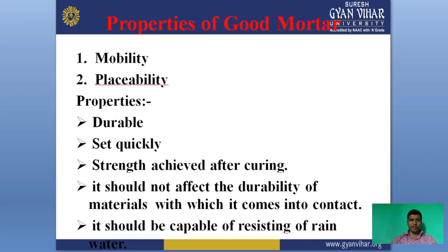The good properties of a good mortar are: it should be durable, meaning long life, and it should set quickly, in very little time. Strength is achieved after curing. It means we have to place the concrete and give water for the curing process, then we will achieve further strength.